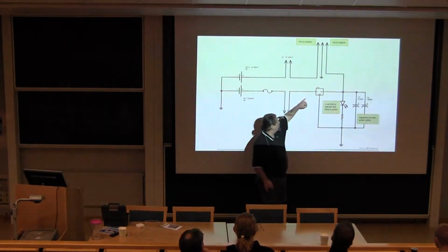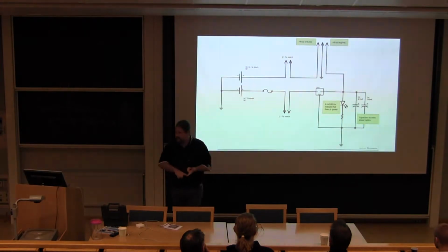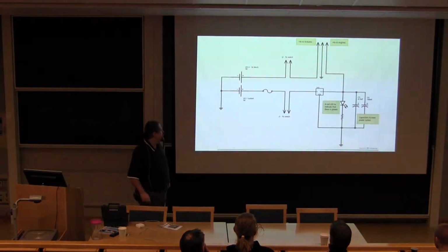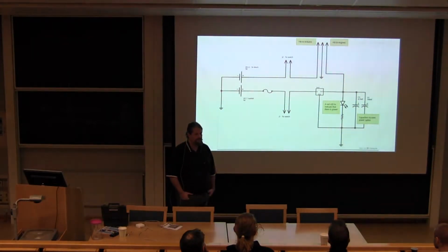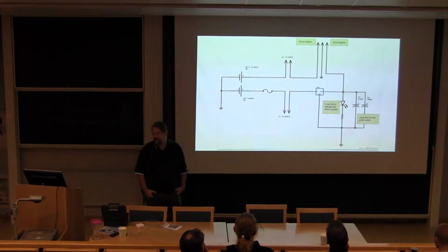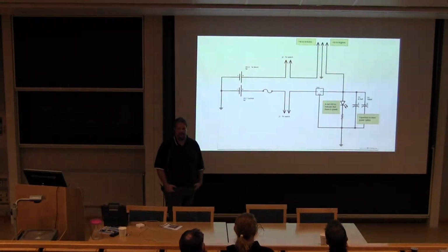And I have this power regulator circuit that takes in somewhere between 5 and 35 volts, and the output is always 6 volts. It's recommended that the input is from 7 volts, so it actually gets to 6 guaranteed.